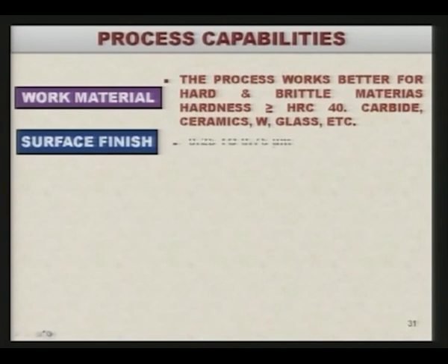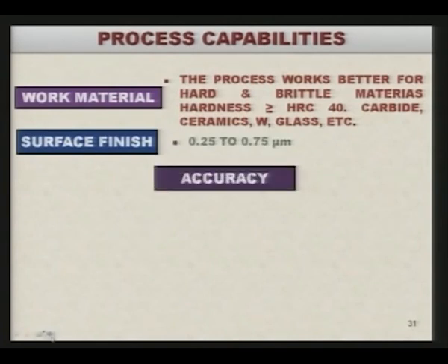Surface finish that can be obtained by this particular process is in the range of 0.25 to 0.75 micrometer. However, all this will depend upon the selection of the parameters of the ultrasonic machining process.